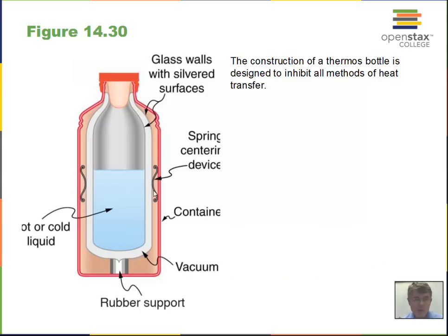And then just light contacts between the glass wall and the outer shell, again, not giving much opportunity for the movement of energy. Having a small area will lead to a small cube. And then the container itself and the silver wall, having silver on it reduces the radiation. If we would have a clear flask out to the outside world, then the temperature would increase quite a bit. Light would carry energy away from this object, if it's hot, to the outside world. But having a silver coating on this thermos bottle reduces the amount of radiation energy that's carried. So this device is built to minimize the movement of energy from the hot region to the cold region.